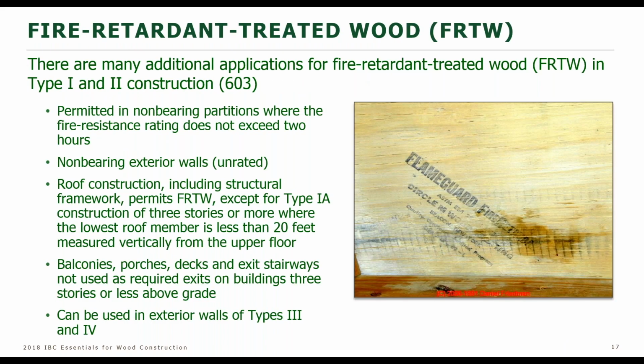Speaking of 603, across all the construction types, fire retardant treated wood is permitted in certain locations. Certainly, even in types 1 and 2, non-bearing partitions can be fire retardant treated wood, with some limitations. Non-bearing exterior walls can be fire retardant treated wood.